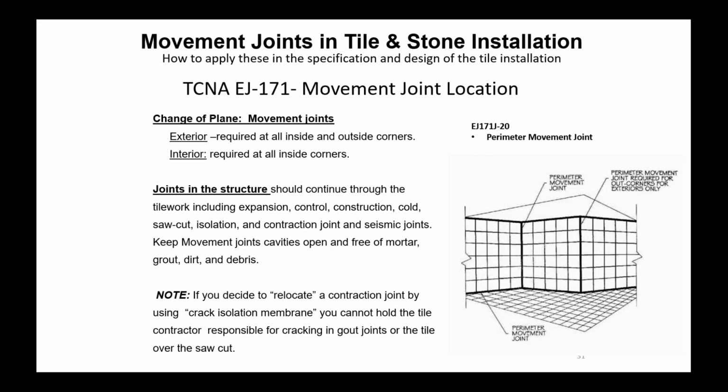Many membrane manufacturers will allow for things like this, but you've got to check on a case-by-case basis, because today with large format tiles, F125 has two methods, partial and full. With large format tiles, there is no partial. You really have to do a full installation of it. So there's going to be caveats more than likely if you're going to do this. So I suggest reaching out to your setting material manufacturer and getting specific recommendations if you decide that you want to bridge saw cuts.